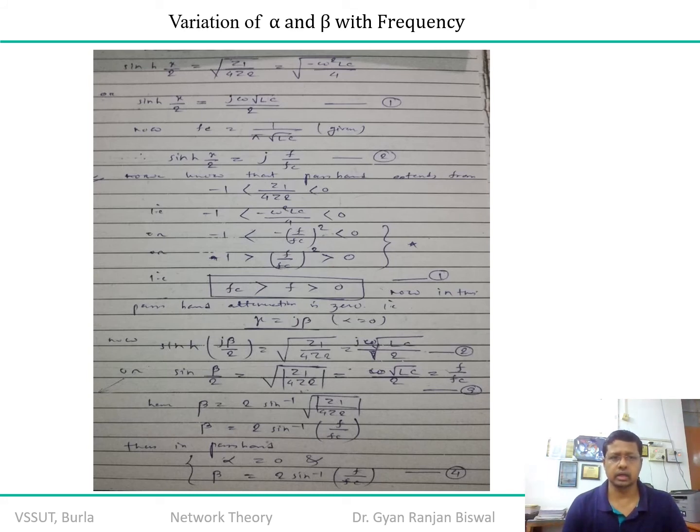I would also suggest you investigate how the cutoff frequency, which is a component of your LC, as far as LC type filters are concerned, can also be represented in terms of gamma, alpha and beta, that is, the attenuation constant alpha and the phase constant beta, and how these are relevant to the propagation constant gamma, and how gamma further relates to the pass band attenuation, in terms of the pass band and the stop band.